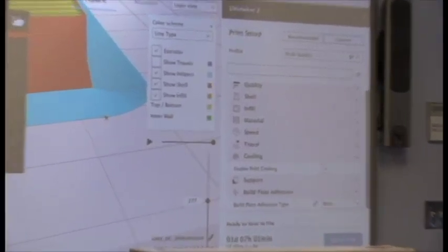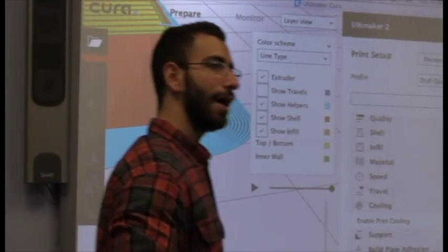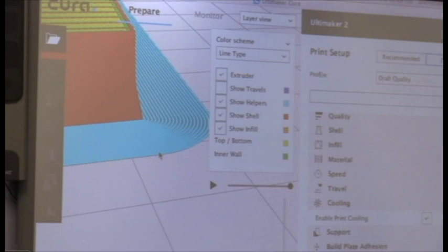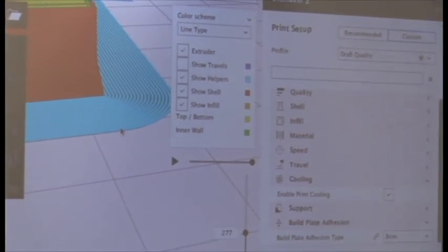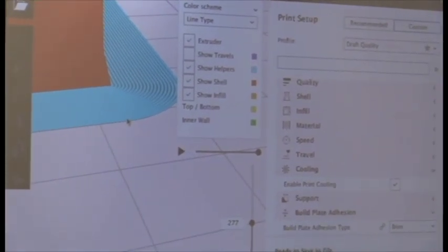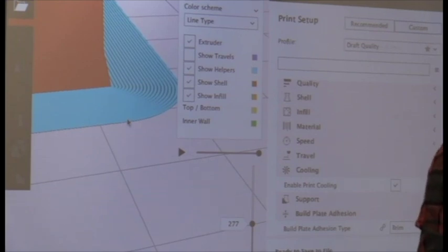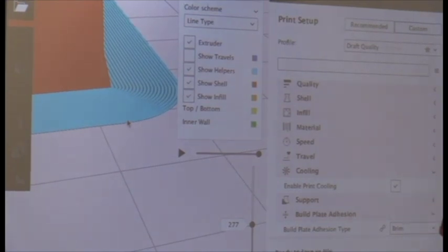So a brim is used for adhesion. It's added on the outside to increase the surface area that the whole thing is being held onto. Always add glue. That usually works. Preferably there's another brand that's like purplish, something like that. I don't remember what the name was. I'll show you guys. But whatever I have there, I always have some sort of glue there. Use that. You don't want the print to come off. And also, if it does come off, sometimes it lifts off. That will also give you work. That's extra for you guys to know.